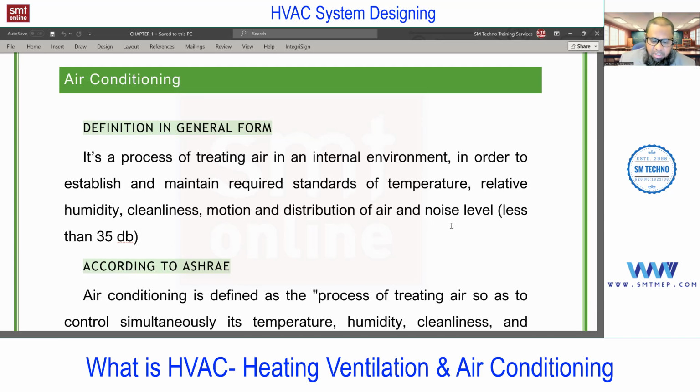If again it is a machine with an operator, then for the operator, for the human, we need to maintain the noise, or else he cannot focus on his work. But if it is a self-operated machine, in that case we can ignore this point, and even RH we can maintain less than the standard, less than 30% as per the equipment requirement. And if you talk about human comfort, the noise level should be less than 35 decibel, because less than 35 decibel means it will not create irritation or disturbance to our ears.